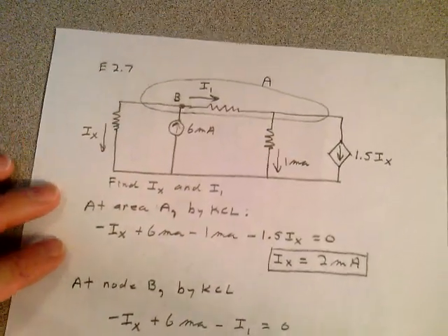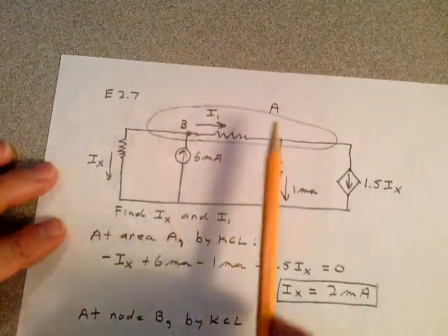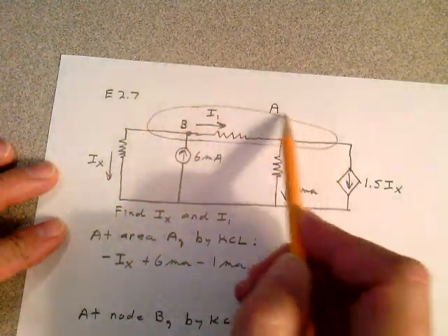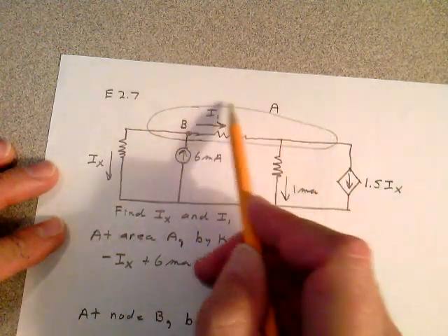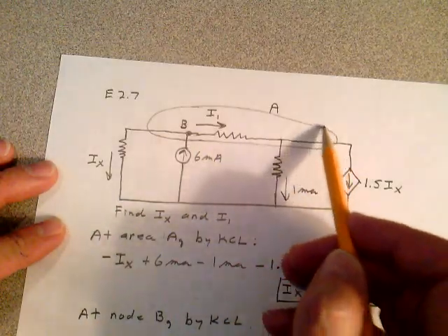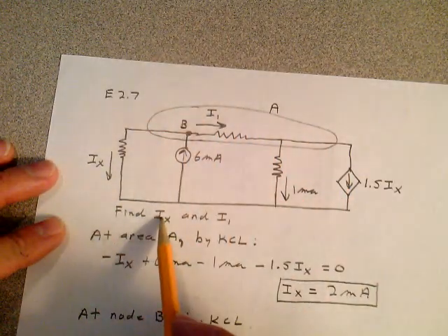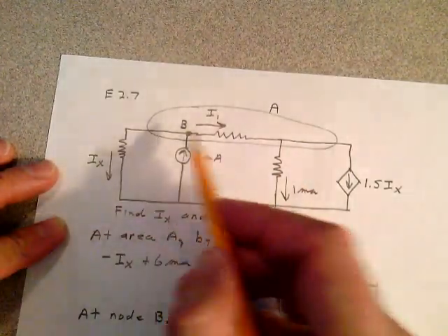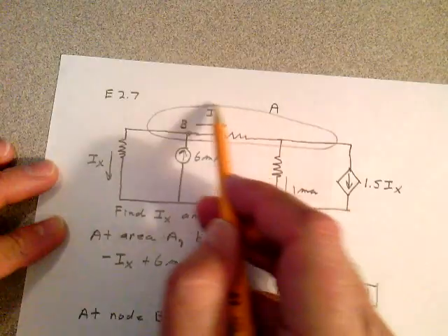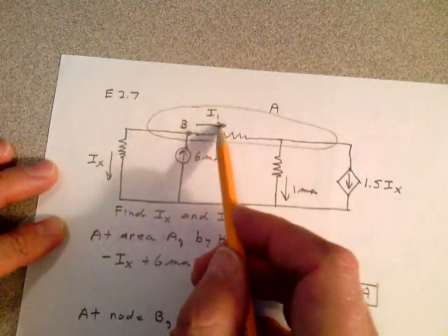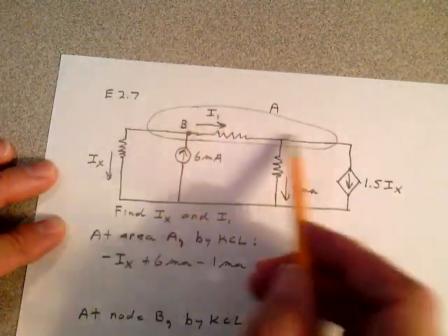Let's start out at 2.7. How'd I get 2.7? Well, in 2.7, I treated this as a surface. We're going to refer to this as a super node when we get to chapter 4, but in any event, just treat this as a black box. This is some part of the circuit here, and you have to find Ix before you can find I1, or you'll run into difficulty here. So just treat this as one big node. It's really not a common node because there's a resistor in here, but currents flowing into this cloud have to be currents flowing out of the cloud.